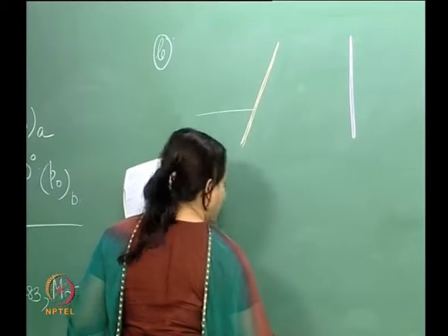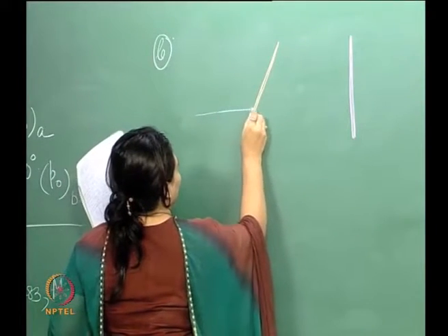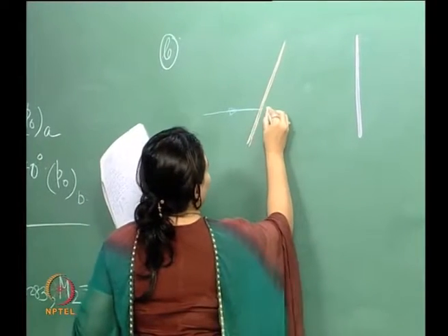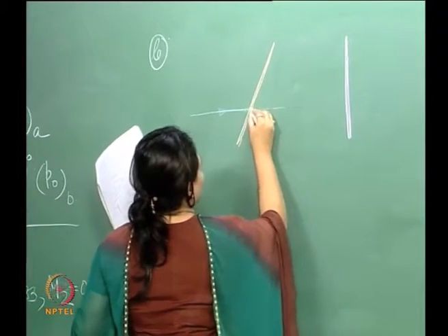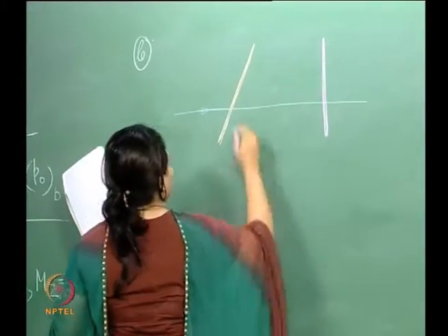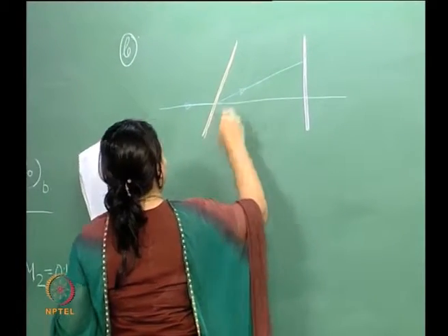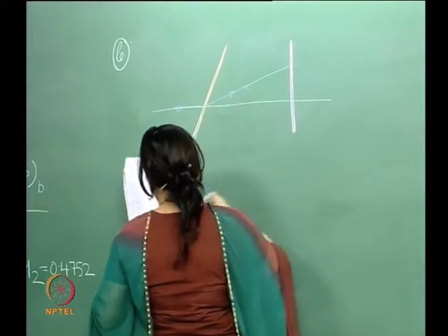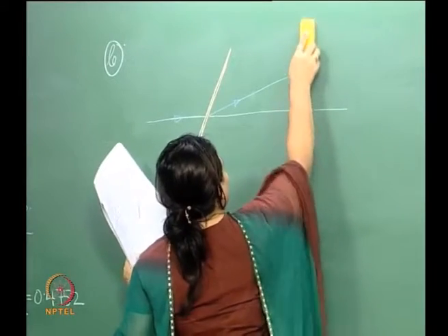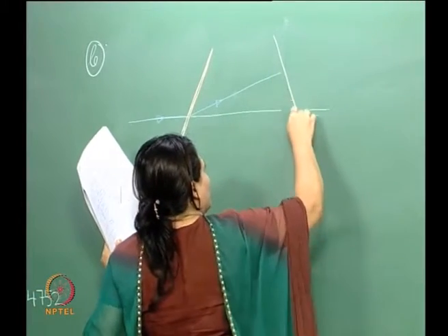look at this free stream here, okay, so I have this, and then this free stream is deflected, right? The free stream is deflected like that, and since this has to be a normal shock wave, what I'm going to do is keep my shock basically normal to this.